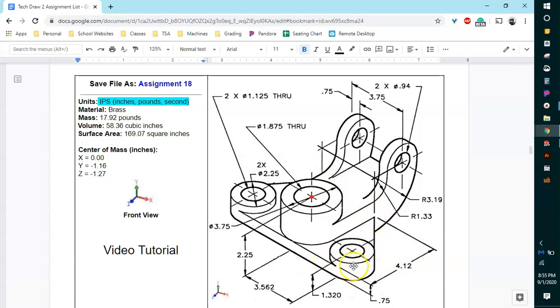Okay, and now these curved corners are actually going to be raised up cylinders later on, so that'll be a second drawing. So right now we have to know what that radius is of that curved corner. Okay, well, it says it has a diameter of 2.25. That's when it's a complete circle. So what we need to do is just divide that by 2. And you can either do that in your head or have SolidWorks do it for you.